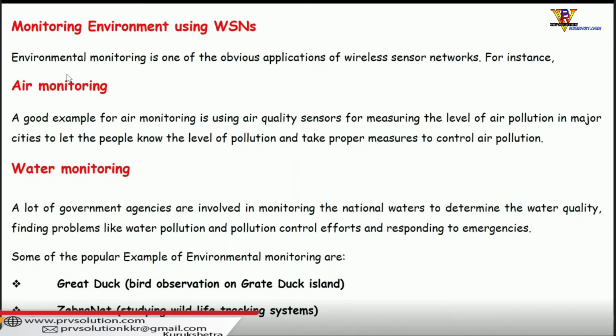But it is not the only indicator for quality of water. TDS may be good, but other things may be there, because the TDS sensor cannot measure the presence of fluoride in the water. It cannot measure the silica content in the water. But I am taking just an example to get some value of TDS so that we could decide whether it is safe for drinking or not.